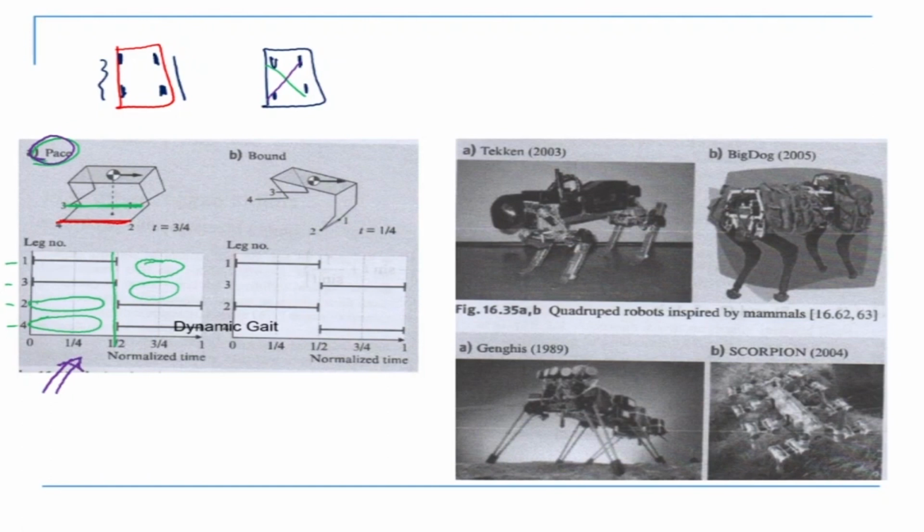Okay, so the other gait is the bound gait. This is my bound gait, which can be used for running or jumping also. In a bound gait we have 1, 2, 3, 4 legs. So we have 3 and 4, which are in air, that means the front legs are in air. Okay, it is like this. These two are in air. Then in the next shot, 4 are on the ground, and then this is in air.